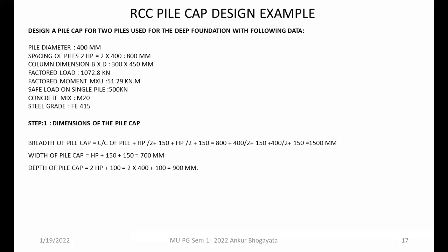But definitely there are some typical steps. Now please understand, here I have just taken a solved example of two piles in a group, and for that we are designing the pile cap. Designing the pile cap for more than two piles will require some sort of modification. This modification is always in terms of calculation of the bending moments, basically in X and Y directions.